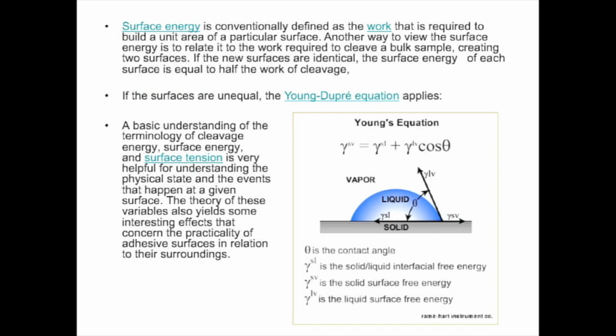Now, basic to adhesion, of course, is differences in surface energy. And the terms hydrophobic, superhydrophobic, hydrophilic are associated with wetting behavior with water. So this very basic formula called Young's equation allows you to measure the surface tension difference between the air-water, water-solid, and solid-air interfaces, which is governed by this cosine theta. So the higher the cosine theta value, the more the liquid or adhesive wets the surface. The lower the cosine theta, the more it hates the surface or prevents it from wetting.